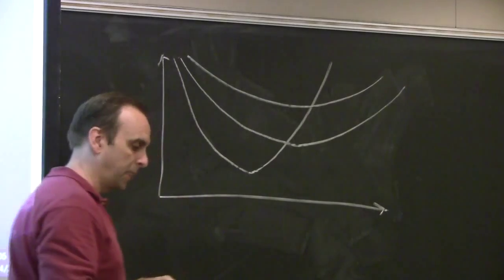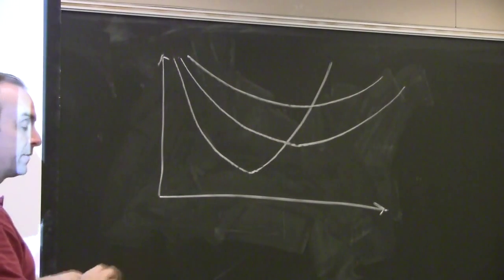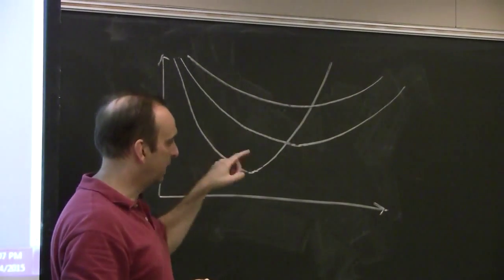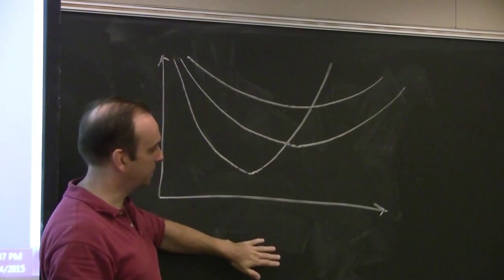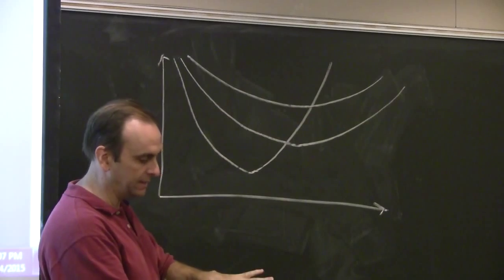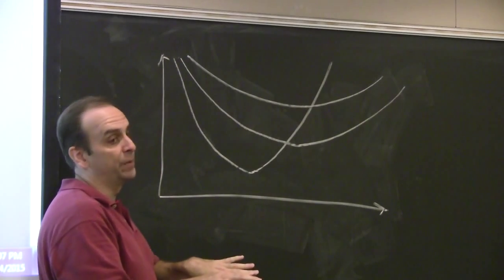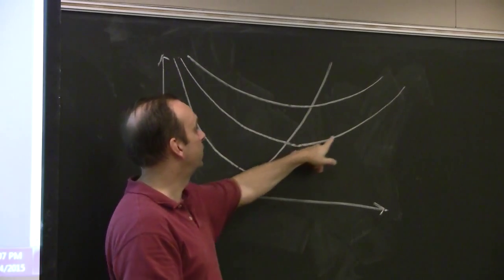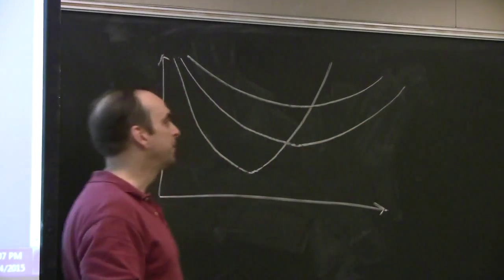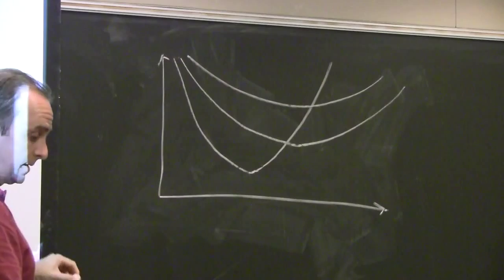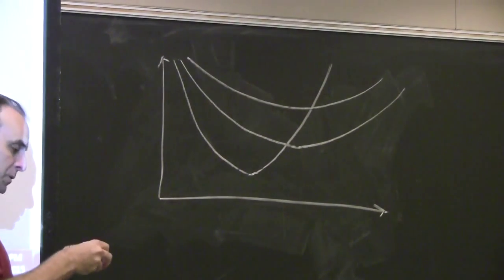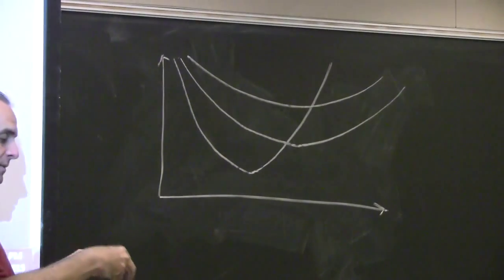And in fact, if you're looking at a board and you're powering something that's very high frequency, like a processor or whatever, putting capacitors on the board, even small surface mount capacitors right up against the ASICs, at some point really have no impact because you're out beyond the resonant frequency. You're out here somewhere in the right-hand weeds. So they have to get exotic, and they have to place the capacitance closer and closer and closer in toward the ASIC, so they're fabricating it in part of the part.